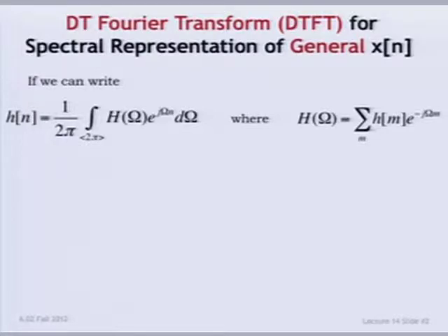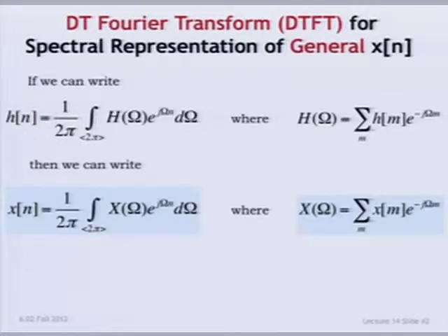And what we said last time was that what you're doing with a unit sample response, you could actually do with any signal. So you can take any signal x of n, compute from it the DTFT, the discrete time Fourier transform, with the same formula. What you get is this object that can be used then to reconstruct the signal, again, the same formula. So there's just a change of perspective.